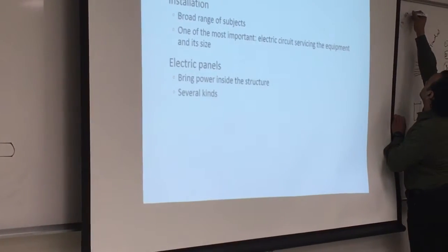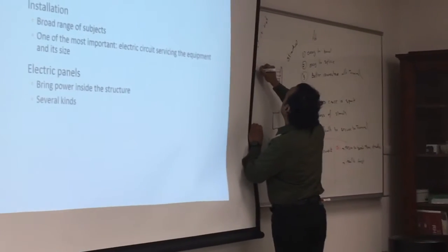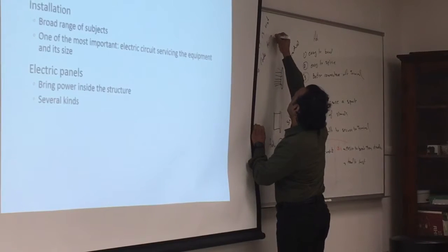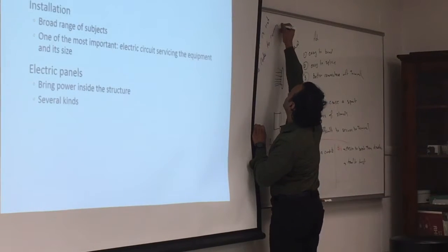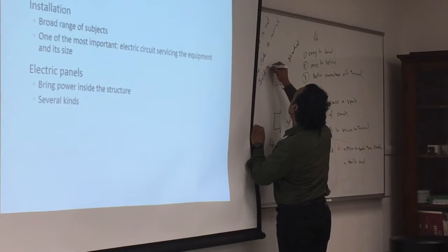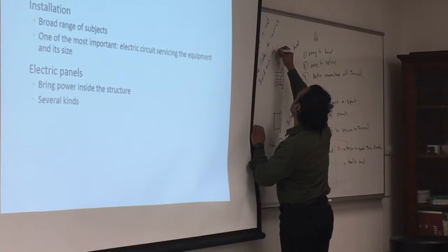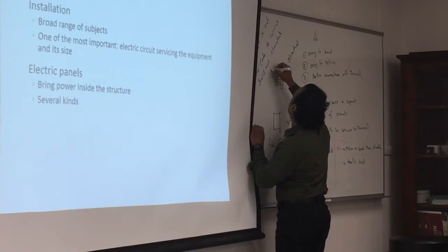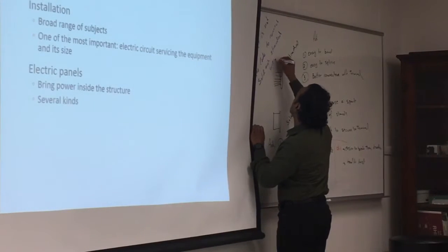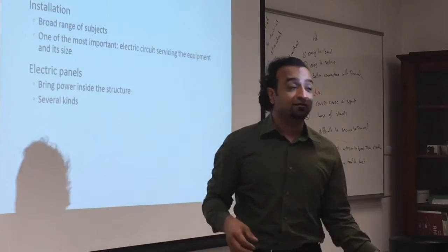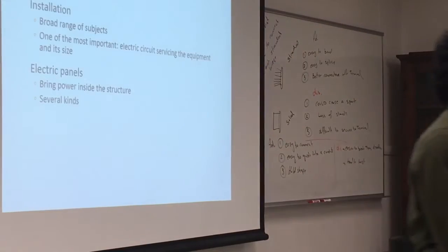It is not the code to connect solid and stranded wires. People do it anyway, but it's not the code, just so you know. If you have somebody inspecting your work, they will probably look at that.